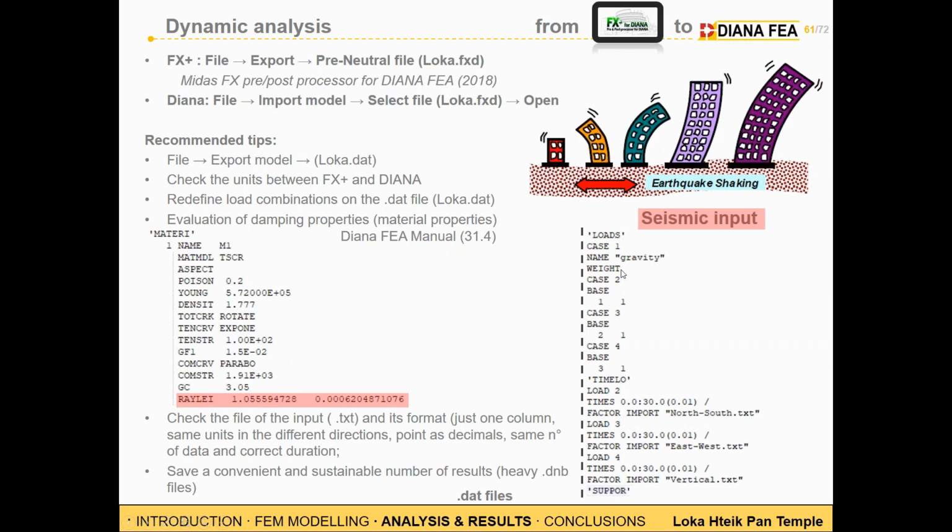And then we can talk about the base excitation load. Base excitation is the option we have found before in the graphical interface to apply dynamic inputs to the structure. The first number, the first string refers to the load we want to apply, such as base excitation.